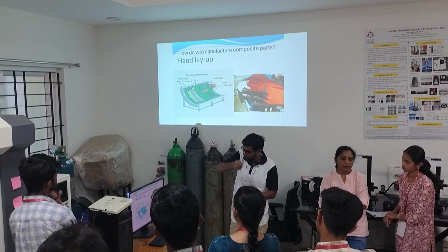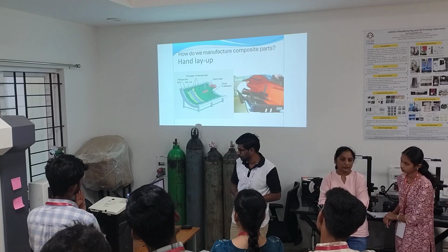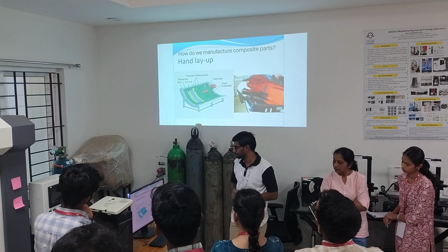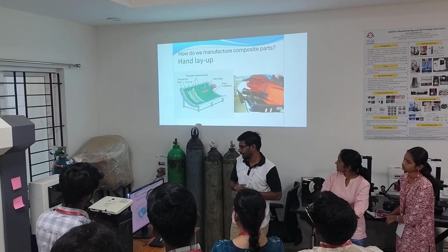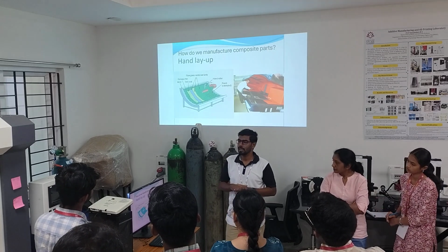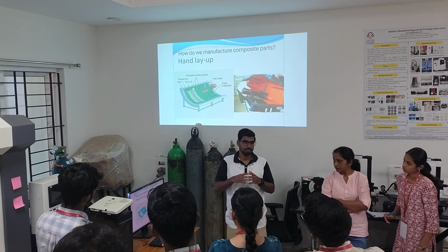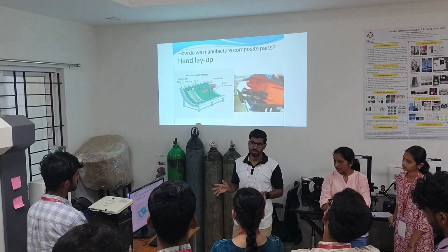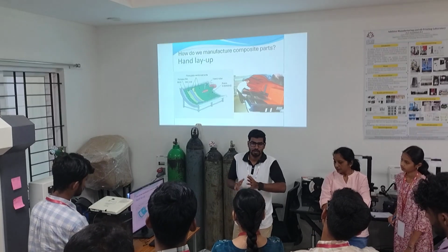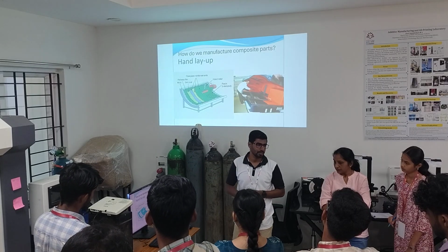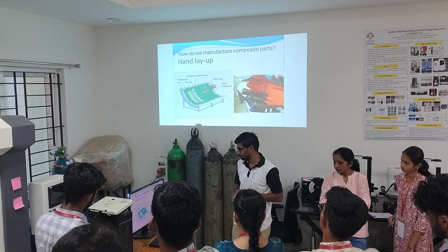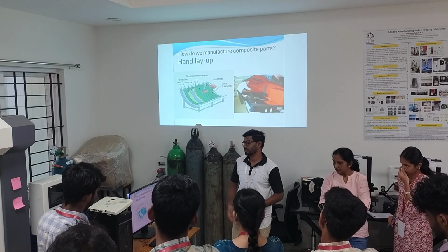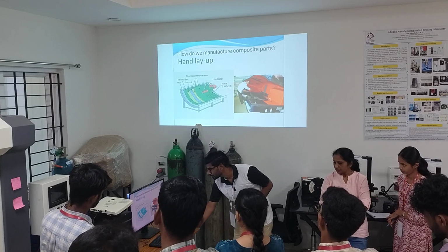And then with the help of a roller, you can see a person making a huge component just out of this hand layup method. Here the biggest advantage is that you can make components as big as you want. There are no restrictions on the size, you just have to make sure that your mold is as big as you require. Nowadays even boards are available where the whole board itself is made out of composite fibers.